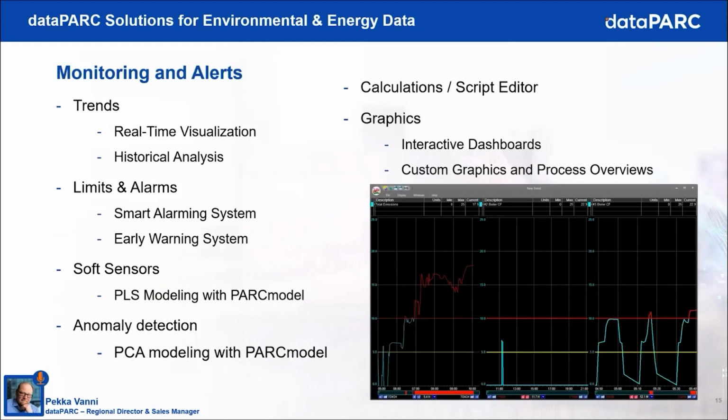In the information applications, you typically visualize the data with trends and control limits, as the system generates alarms to secure situational awareness. Trending is applied for real-time monitoring as well as analysis of historical data. KPIs are made visible for everyone. Performance is transparent, and continuous comparison to configured limits, emphasized with smart alarming systems, are the core elements of today's management system.